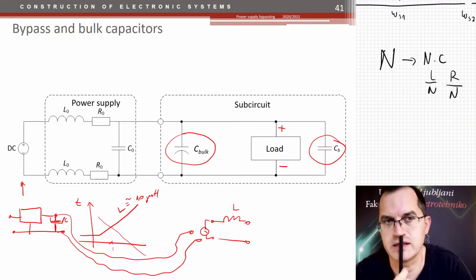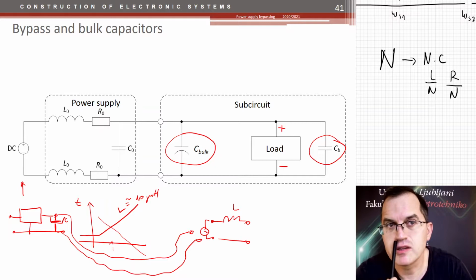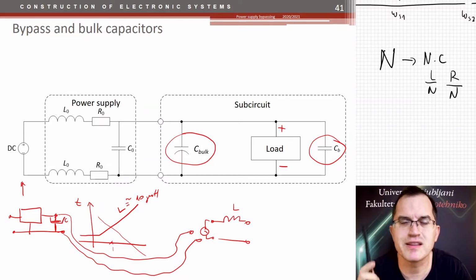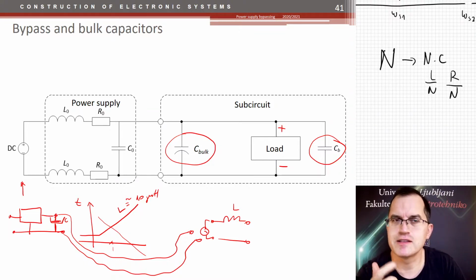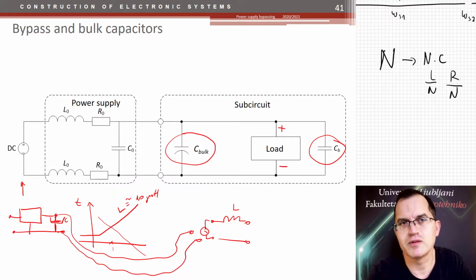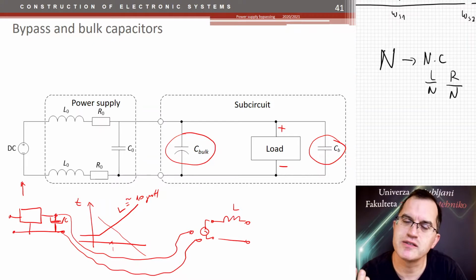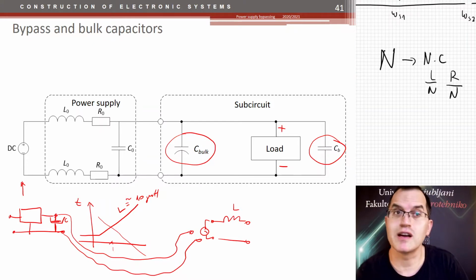And the other thing is, the bulk capacitor, because it is very large, is not a very good quality capacitor, but it doesn't matter because it has to act at low frequencies. And if it's not very good, then it might also be good for filter damping, because the series resistance would be maybe just the right one.